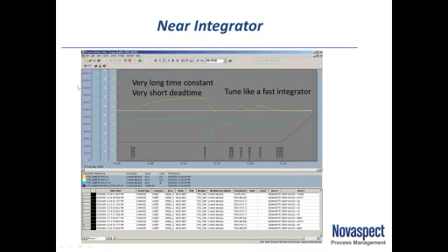In this loop, it took over 10 minutes. I made my bump change on this self-regulator. It took over 10 minutes to get there. Now what that means is, first of all, I'm sitting here twiddling my thumbs, wasting 10 minutes waiting for that. Second of all, I'm not confident that everything else in my process is going to stay constant for the duration of my test.